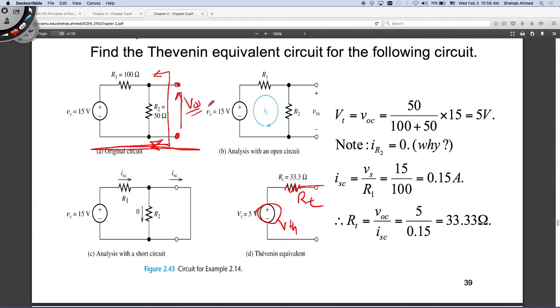No, there's no trick. There's no similar trick to find V Thevenin like R Thevenin. No, there isn't. Good question. R Thevenin, there's a trick to find it quicker. V Thevenin, no, you have to solve the circuit. You have to find the open circuit voltage between the two terminals you are looking into.